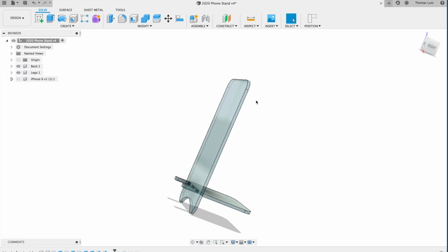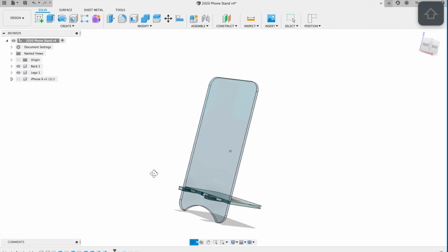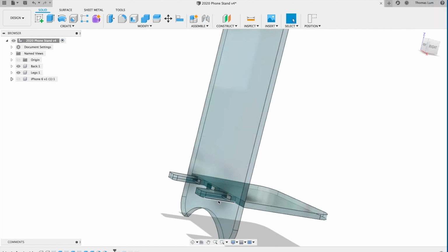And acrylic, although you buy it and it says an 1/8 inch or 3 millimeter or 4 millimeter, it really isn't. It's like kind of buying a 2x4 and realizing it's 1.5 inches by 3.5 inches. So same thing with acrylic. We have to measure the thickness of it, and each one's different, which wouldn't be a big deal, except we need to know that thickness when we're designing this part.